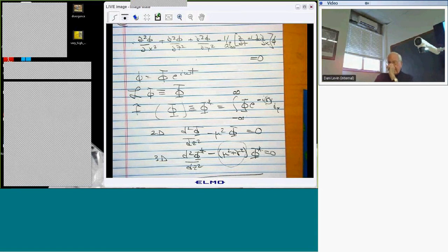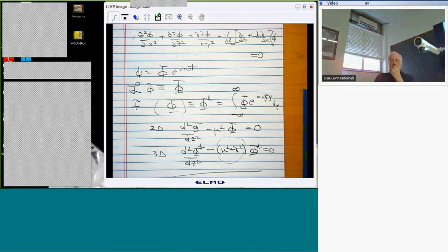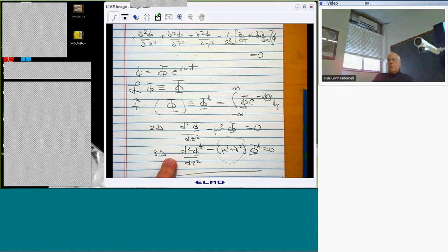In fact, there's an alternative way. We're going to do subsonic flow, and we'll use a somewhat different method in subsonic flow, although formally similar. In subsonic flow, we cannot take the Laplace transform with respect to x, right? Because things are happening for x less than 0, because we're not moving fast enough to keep ahead of the speed of sound.